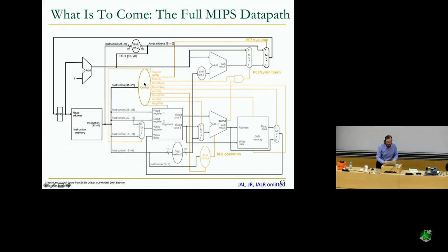You can see the control signals, right? They basically determine which input of this MUX is selected, what the ALU should do, and how the next instruction address should be determined. So for example, if it's an unconditional branch, the next program counter should be set based on the result of the ALU over here, right? Which is the target address computation. And also whether the destination result, if the instruction is writing to a register, should come from memory or the output of the ALU. That MUX is controlled by a control signal that's generated by the control logic, right?